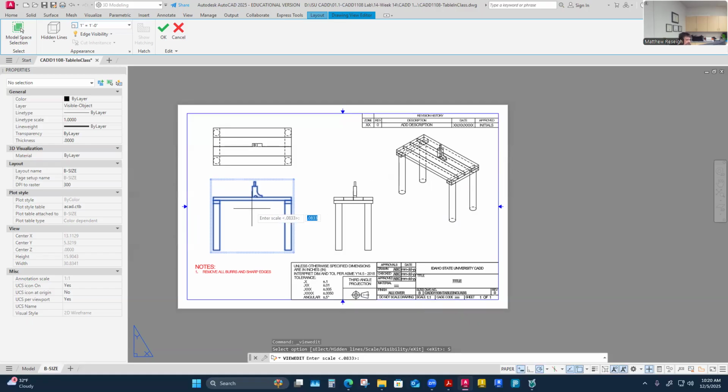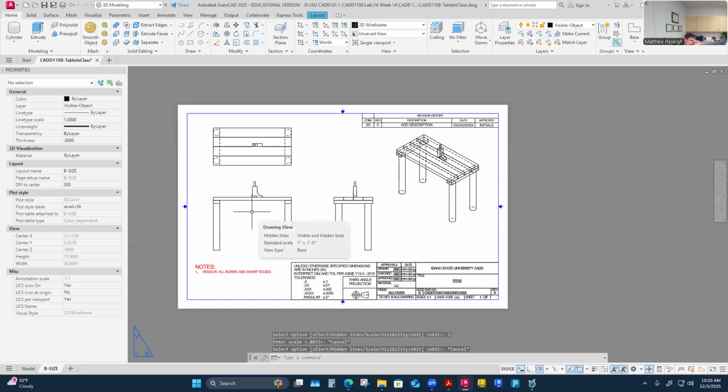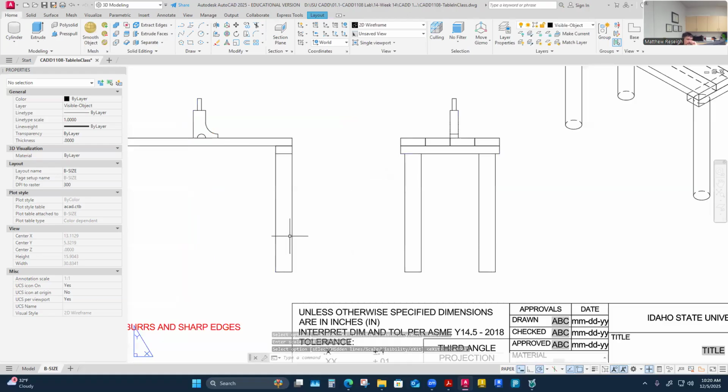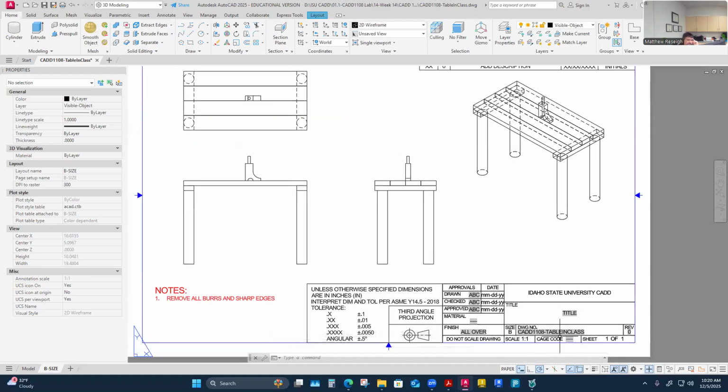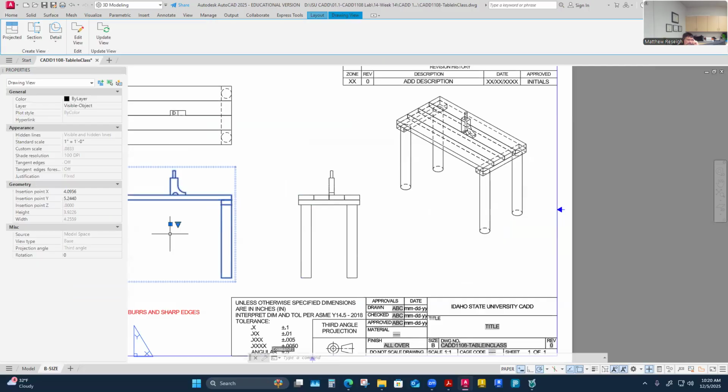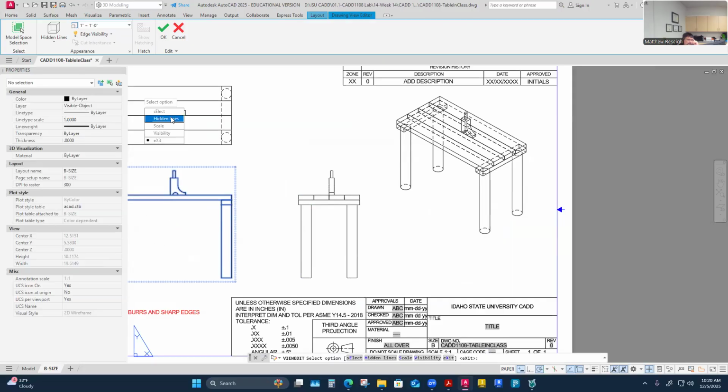So they can be a little bit different. 0.083, that's a little bit bigger than a 16th scale. Pretty small scale, actually. It's kind of a big table to fit on this drawing. So I'd probably just keep it in a decimal scale and just adjust my ratio accordingly on my title block. The other thing I want to show you, as I wrap up, that's the scale.